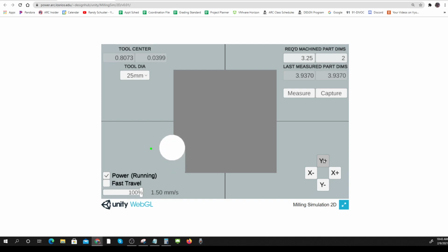And this speed is about right for a Bridgeport mill. You can go beefier and really move faster, cutting a fairly hard alloy steel. Okay? If you're cutting something else, you can move faster, but we've got it set for this. Okay, so here we go.